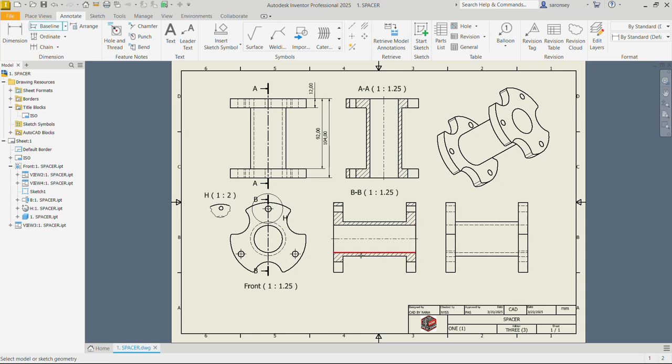Now let's do same for this sectional view. Let's pick the baseline here. We'll pick this line as well. Let's also pick that and that. You right click and continue. Now you take that down horizontally, so we get these dimensions. Just click, you right click, and done.